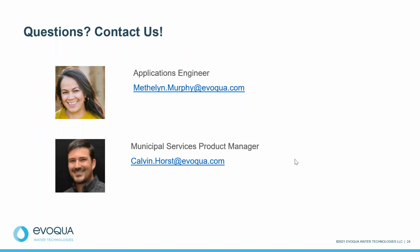So starting with the first question, Matthew, will a pH shift product create higher sulfide loadings downstream, for instance, at the treatment plant? And if yes, would you recommend complementing pH shift treatment with other sulfide mitigation technologies? Yes, so as I mentioned, pH shift chemistry really doesn't get rid of any sulfides, it just keeps the sulfides in solution.